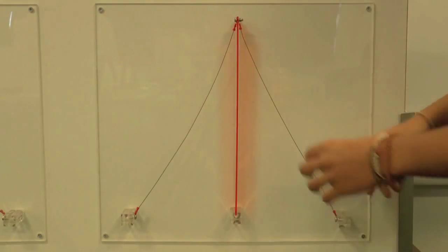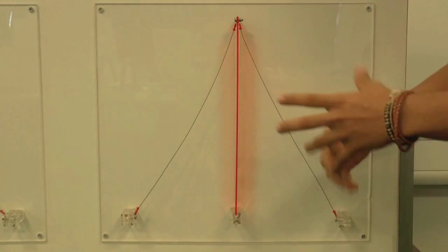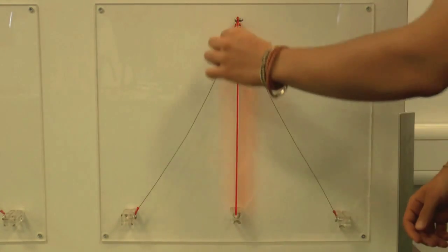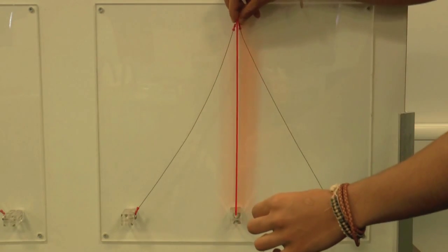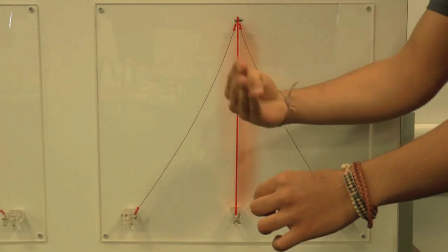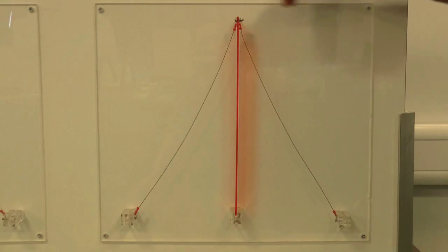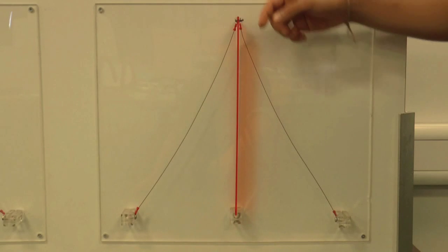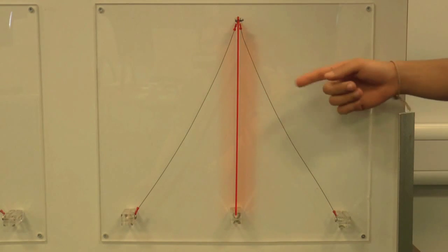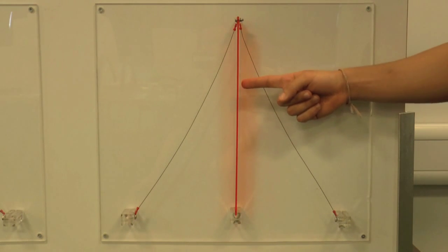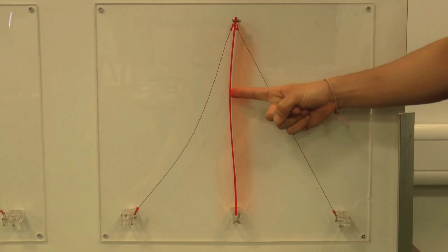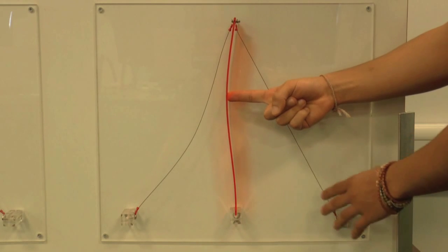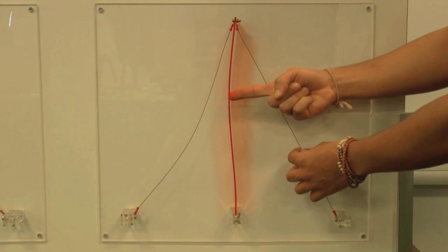But in the real case scenario, we have a 3D plane, in real life a mast. So we'd have a cable spanning out of the plane, supporting it in this direction, stopping it from going forwards or backwards. Okay. So the mast in real life is going to be dealing with a lot of lateral loading from the yard arms. If we have a lateral load hitting the mast here, we can see how it deforms, and the cables act to resist that deformation, to resist the forces.